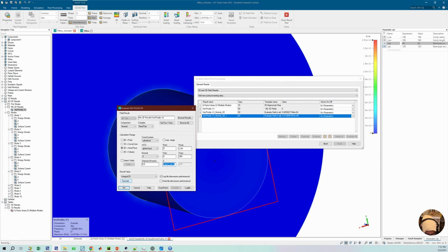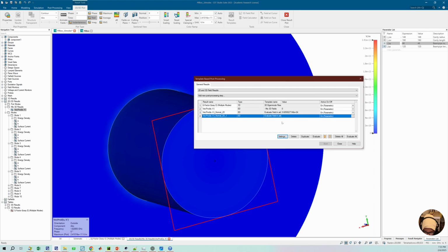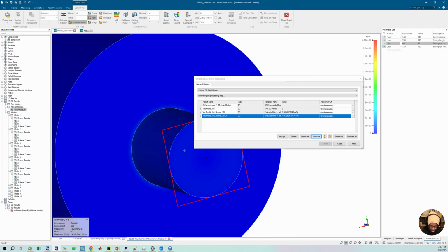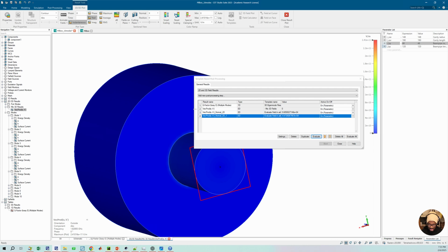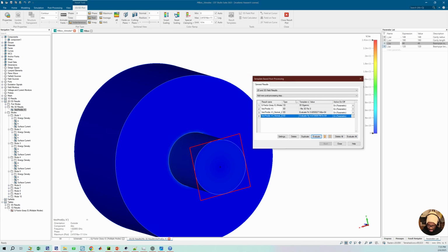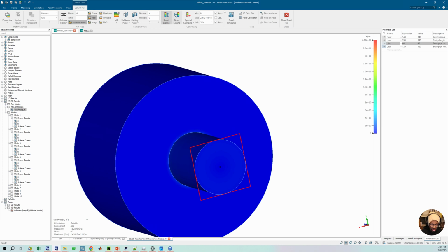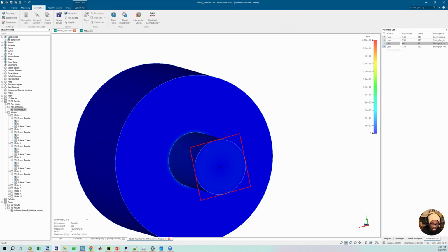Yes, L cavity over 2. So you see that we have some discrepancy. Result is 5.6, and then this is 4.47, so 4.5. So it's different on the faces, even though for this I expect that it should be the same, and I think it's because of the mesh. Now the mesh on the two faces, I'll show you now. Let's close this and then view the mesh. Go to simulation and then view the mesh.